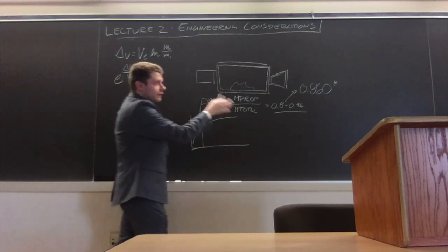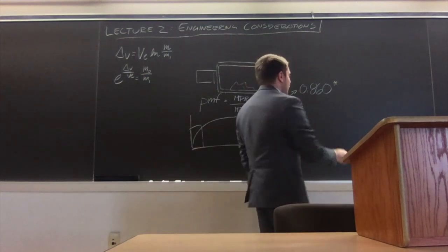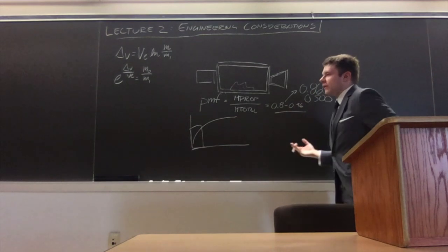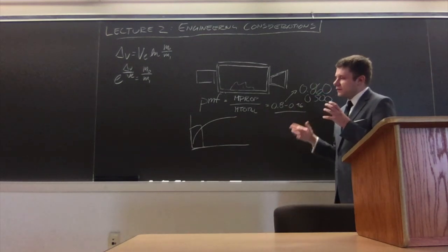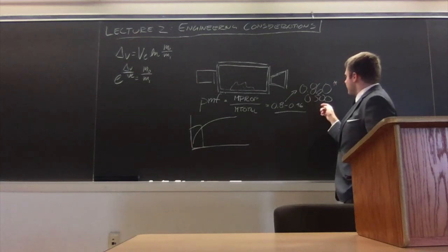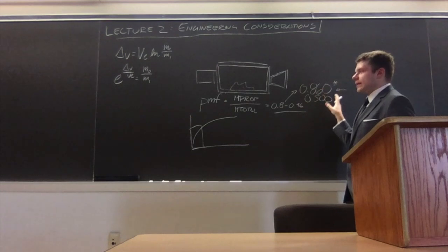So that's why, if you look at this number and then look at commercially available solid motors, you get a number of like 0.5 or less, because they're smaller. They're a little more mass inefficient. You have to constrain that pressure with a heavier pressure vessel. So for our considerations, though, this is generally about the domain that we're going to be playing in.